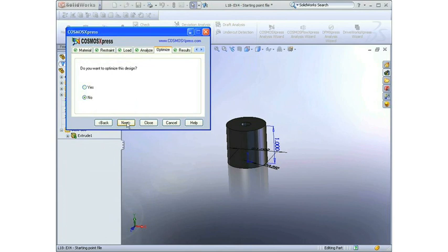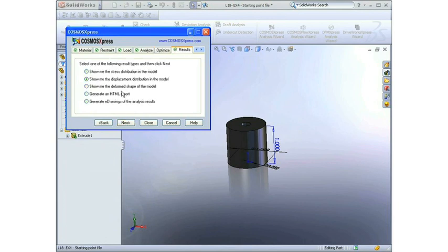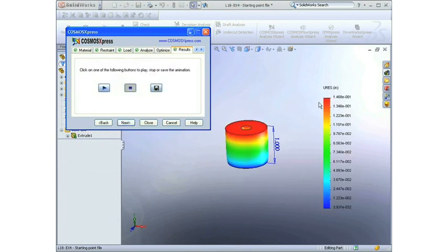We're not going to optimize at first. Let's look at the displacement. Although the factor of safety is well within our design requirements, our current maximum displacement is 146 thou, as shown in this chart. I got that by realizing that the units of measurement are inches, and we have to move the decimal place one spot. So we have 146 thousandths of an inch.